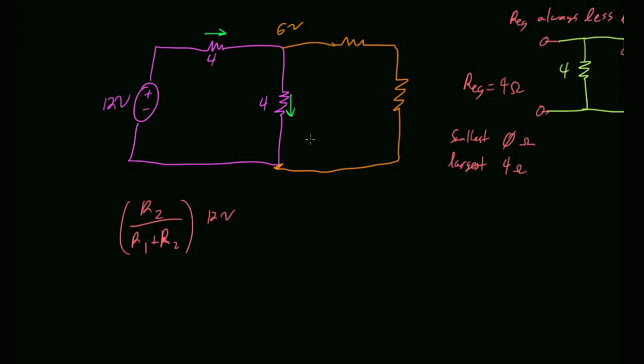Okay, let me tease the next section, and then on Friday I want to work some fairly hairy problems from the book that I thought we could try working. So let's say, for example, let me go back to this. Let's stick with this problem for a minute. Let's say I still want to have this circuit with the 2 branches, but I really want to have this be 6 volts. I still want to connect the voltage divider there, but I don't want any current to get sucked through this branch. I still want this to have 6 volts.